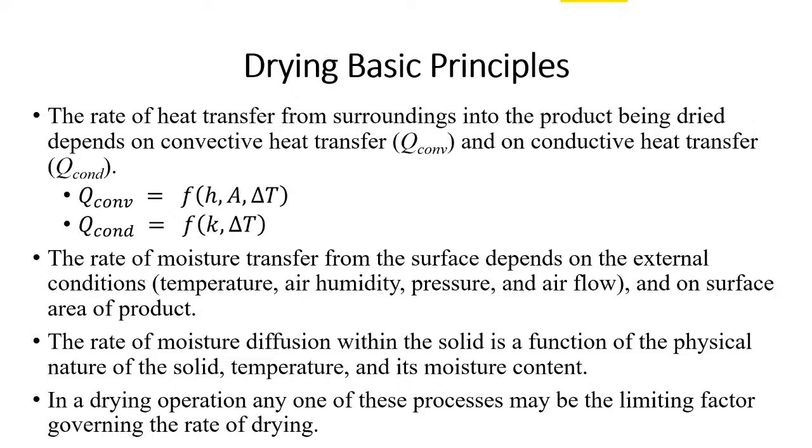The second one is conduction from the surface into the inside of the product. And from the moisture transfer perspective, the moisture within the product needs to diffuse to the surface in order to evaporate.